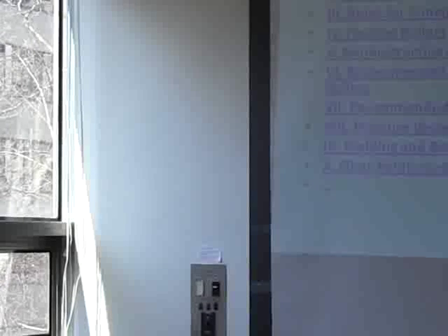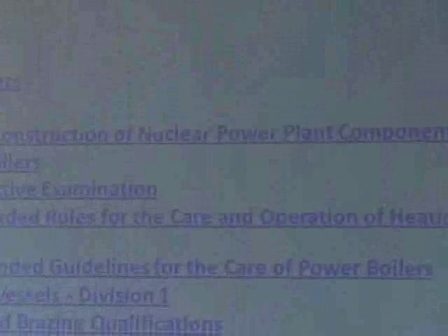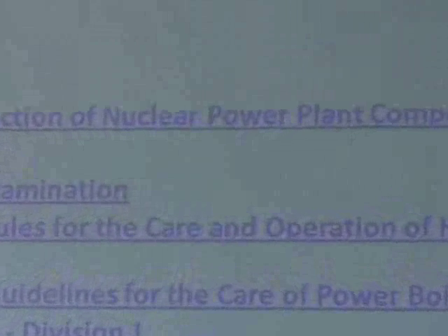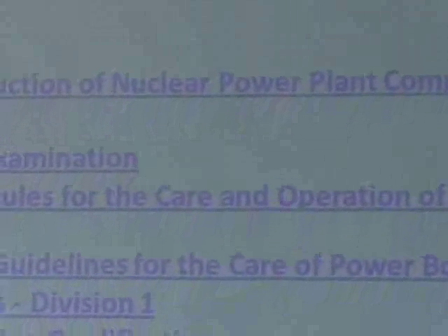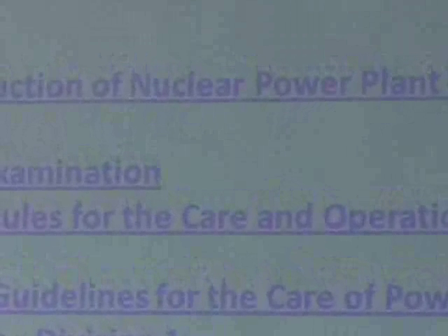So pressure vessels. There's a code by ASME, American Society of Mechanical Engineers, called the Boiler and Pressure Vessel Code. It's used a lot. There are different divisions, which means that there's one division that will give you a very prescriptive approach to design. They'll tell you what to do.